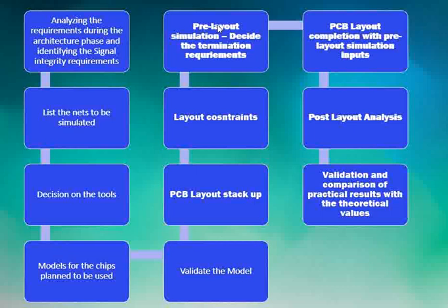And then the layout constraints, the PCB layout stackup, validating the model, all these combined together, he does the pre-layout simulation, and he gives the suggestions, and further the constraints are generated for the actual PCB layout, which will be based on the pre-layout simulation results, and the kind of inputs that are required for routing the PCB.